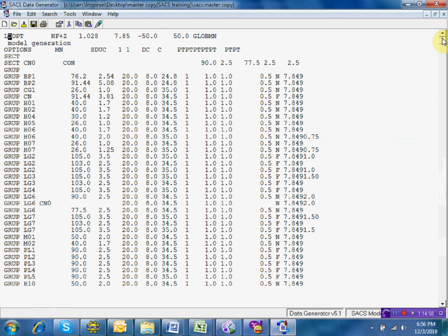So after this one, load combination. We will combine gravity load. Gravity, which means dead load, live load, equipment weight, everything, self weight, and then combine with wind plus current and wave. If there is a rig, you have to add a rig and then the attack direction. So when there is a tender rig, the analysis is quite complicated.